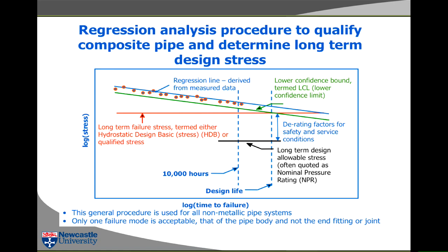But the other thing that you'll see is in the lab, there will be these big vats of water with pipes being tested at constant pressure. You tell me, suggest to me what is a reasonable length of time. You have to be able to extrapolate into the future, up to 20 years or 50 years on a log scale. So what's a reasonable time that you might be expected to carry out these tests for? It's not an hour, it's not a day, it's not a week.